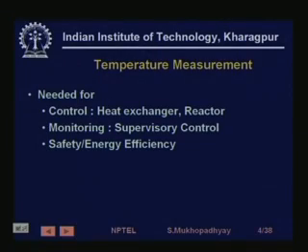Temperature measurement is very much needed for safety as well as energy efficiency. Energy efficiency is actually a very critical task, because large thermal processes take a lot of energy, and much of the cost of production comes from the energy cost, which is rising all the time. So, one needs to ensure that heat is not lost, it is optimally utilized. So, for such purposes temperature has to be monitored at various places on the plant. Similarly, safety, because temperature is often related to pressure and other things. A very high temperature may lead to burns, it may lead to overpressure, it may lead to explosions, it may lead to various things. So, safety and energy efficiency, for these purposes temperature measurement is needed.